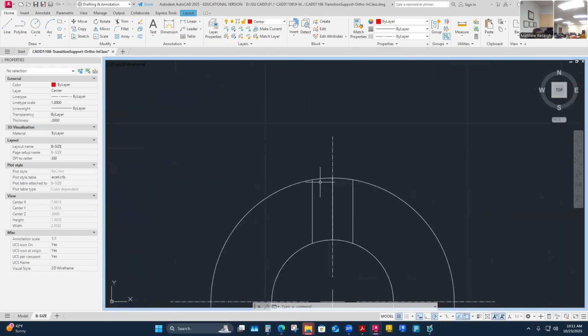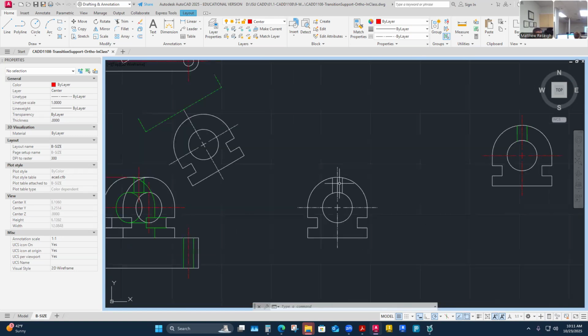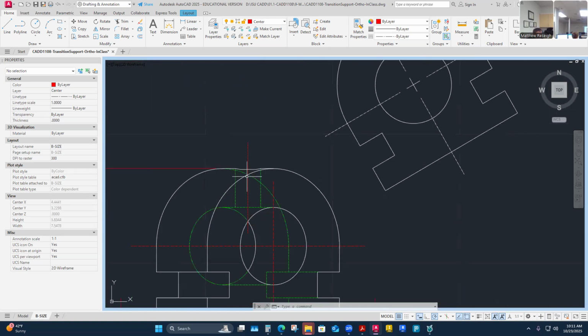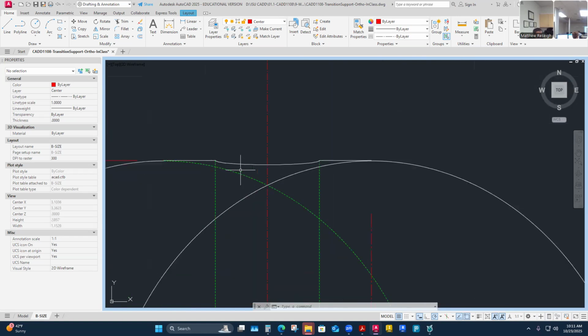I do argue that I wouldn't. You don't think I would see a hidden line here though? No, because it's still curved on the other side of the drill. On this side of the drill it has that curve, and on the other side of the drill it also has that curve. For sure, but you don't think you would see the depression across the center where it was drilled out? If you bored a square hole, would you see a hidden line? No. And the circle is the same. There's no change, a hole's a hole. A hole's a rectangle in that orientation.